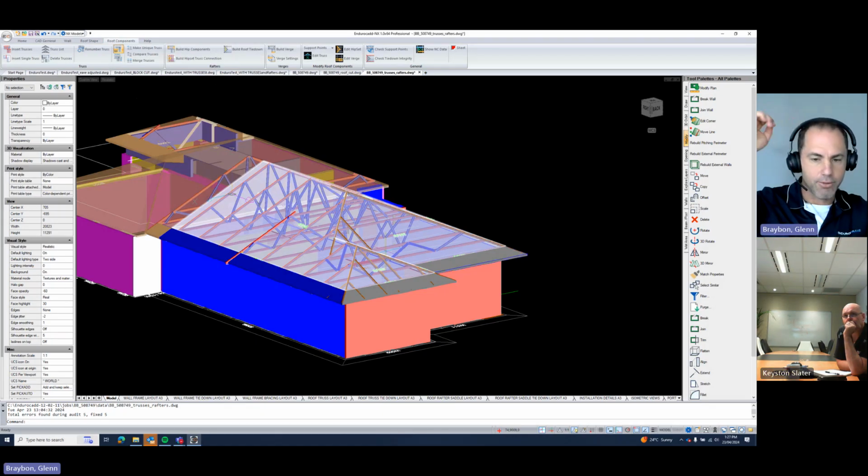And you've got warnings, which are okay. You get a lot of warnings. You get warnings on a truss header because the RF punch codes are within 55 mil or whatever. You get a list of warnings, which I ignore too. But there's another option there to click the severe ones. So it's warnings and severe. If you go to severe, it'll come up with a list of punches that you do need to fix before you send to the machine. Because if you don't, the machine potentially will not roll that file.